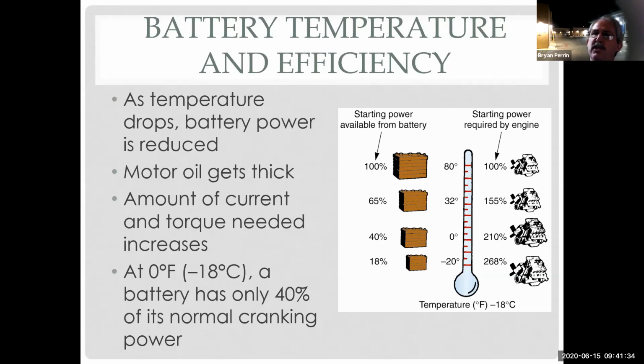So that's one reason why manufacturers specify such a high cold cranking amps. Do I need that on an 80-degree day? No. Do I need it on a 32-degree day? Probably. Do I need it on a 0-degree day? Definitely. Do I need it when it's 20 below? Absolutely. Do they know where that car is going to be sold? Do they know where you're going to go driving? No. So in Southern California, we're spoiled.